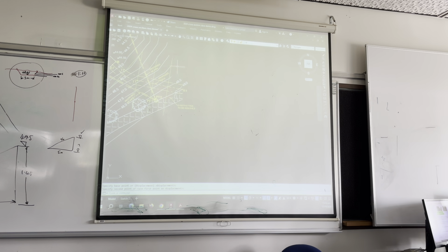Right, so in order to get this cross section looking that way, I draw a line across here. I type the align command. I grab that. I go from the end point to the end point, from the end point to the end point, enter, and scale it, no, enter.